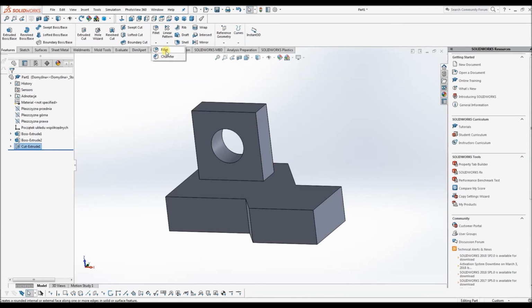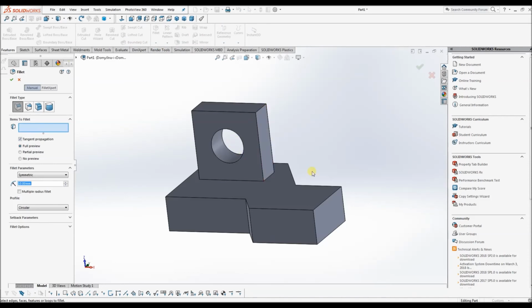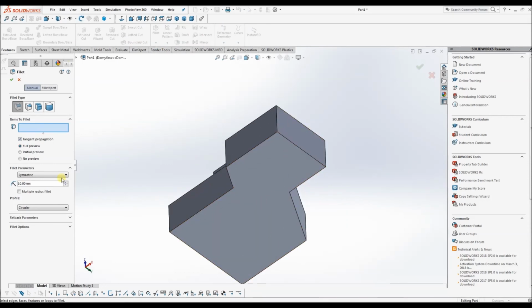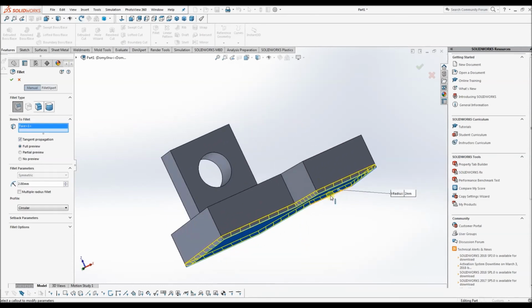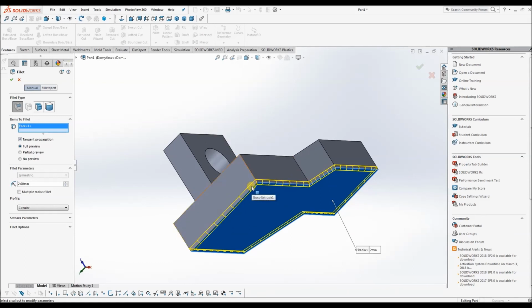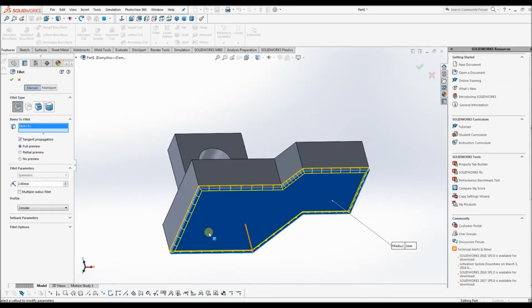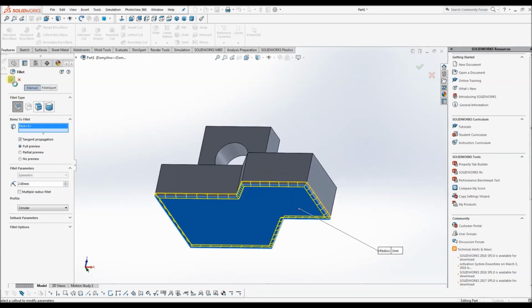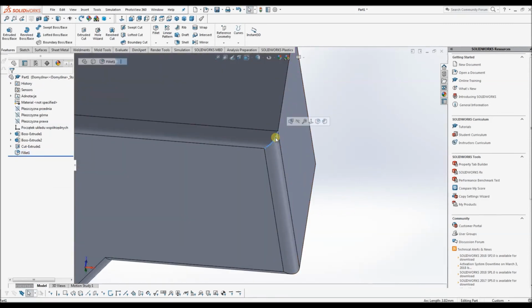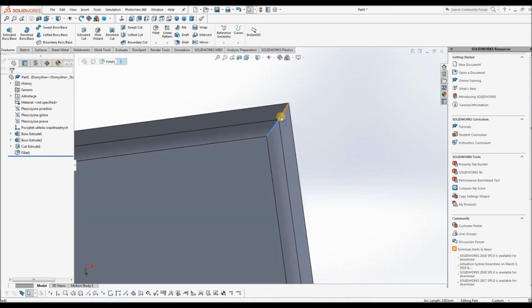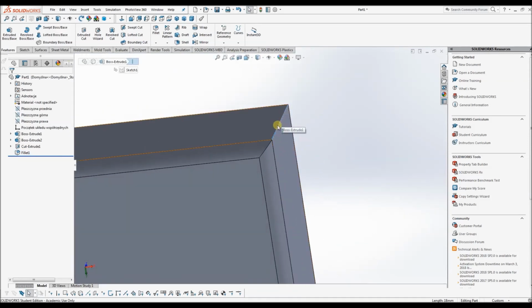So how it's working, basically, if you want to round the corners, for example in here, and make the radius maybe 2, you can click on a plane, so all the edges which are on this plane will go round. So you can make it like this, but in here, for example, you see that it's not looking that beautiful, because in here you have this edge, right?